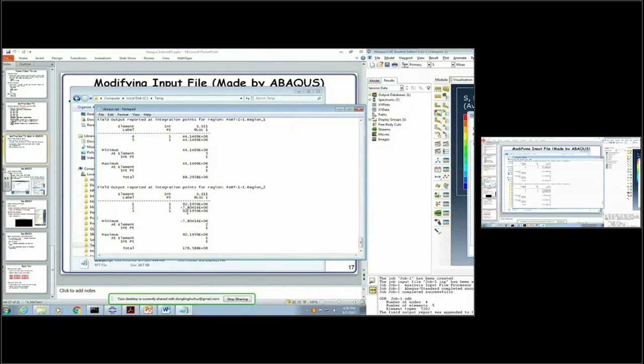So what we should do? Yeah, increase cross-section area to decrease the stress, make it below 80 megapascal. And for the diagonal trusses, it's 44. So we can reduce some cross-section area to make the stress increase, getting close to 80 megapascal, and also the weight of the structure can be minimized. And also for this one, the same. So I think I only have 5 minutes. Let's see what I can do.